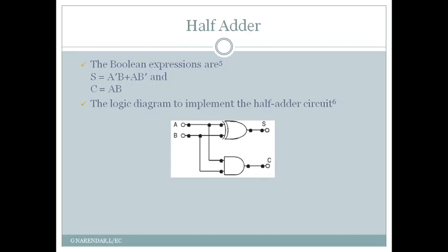As we have obtained our first combinational logic circuit, let's look at whether it gives the same functionality or not. By applying the various combinations of input, we'll check whether the sum and carry output functions are implemented correctly or not.